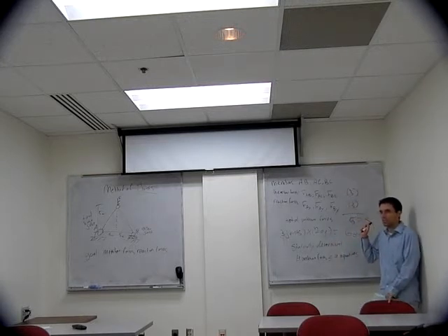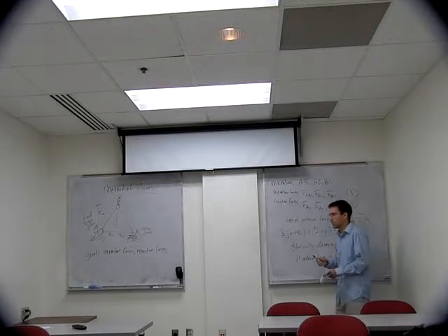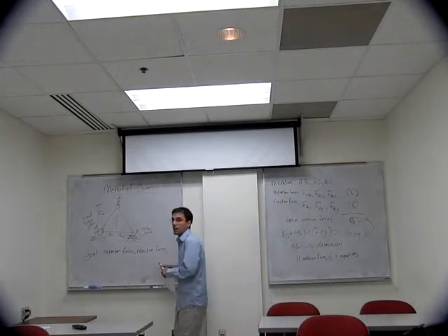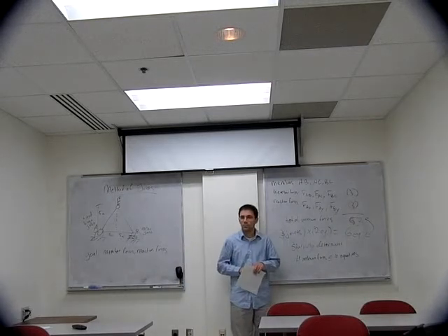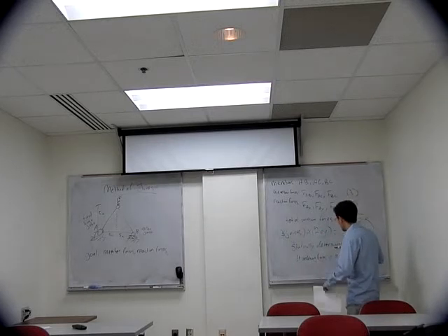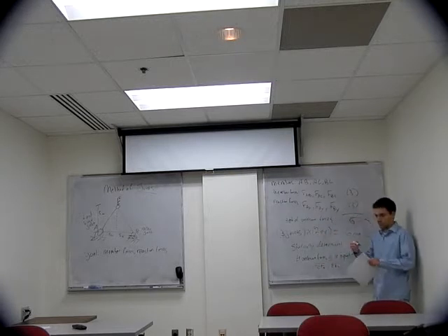We'll see that you can have 0 force members, which is where you get into having more equations than unknowns. Excuse me. So there are 3 joints and 2 times 2 equations. Where does the 2 equations come from? Okay, you'll see that in a second, but basically we know that we can do a summation of all the forces in the x direction and a summation of all the forces in the y direction at each joint.